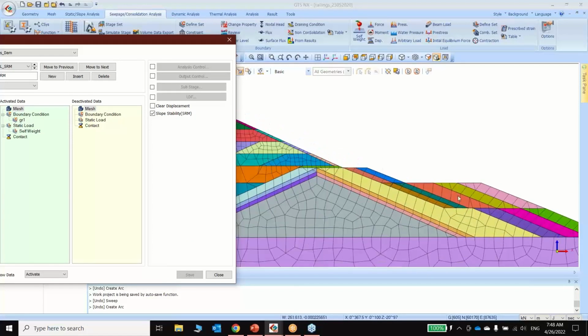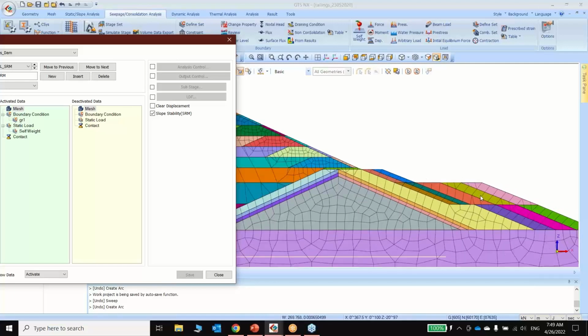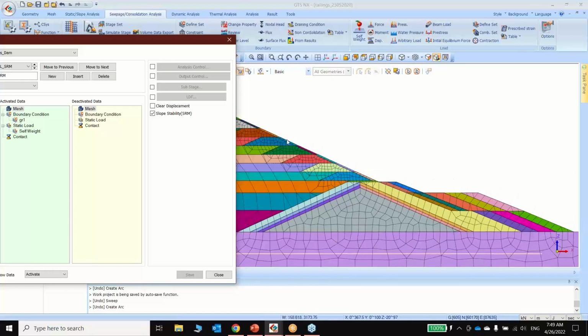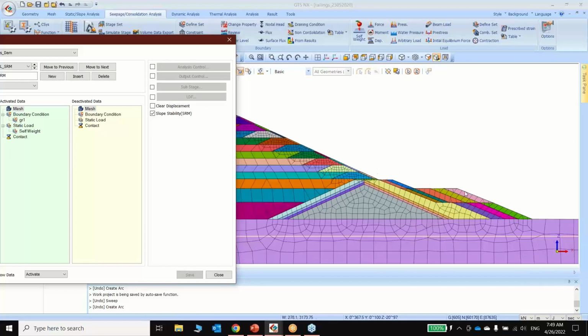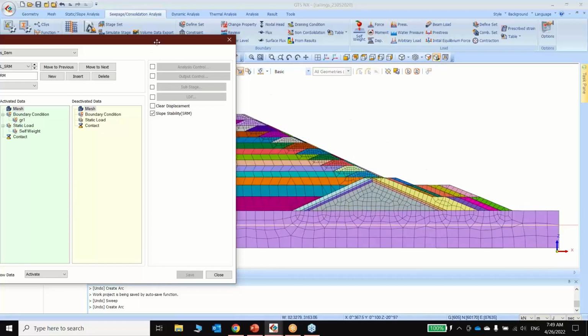But we have designed the rockfill with the same exact slope angle as the original dikes so that the construction is easier and also there is free space remaining in here. That means the rockfill height can be raised from here. If that is still not enough, we can always widen the rockfill in this direction for incremental support during the later stage of the dam.